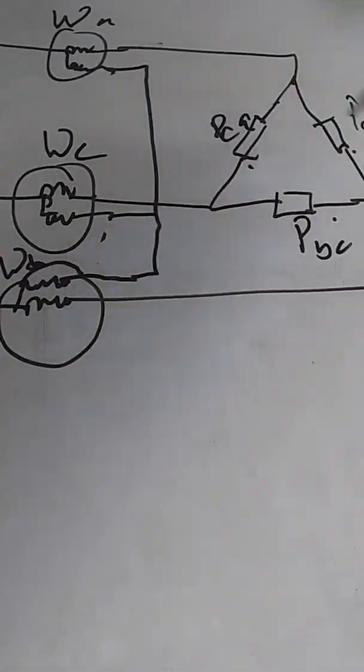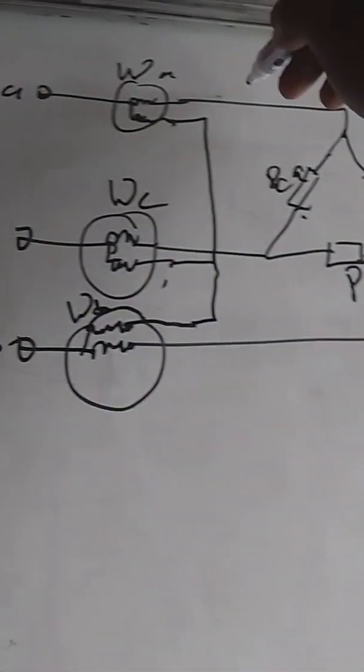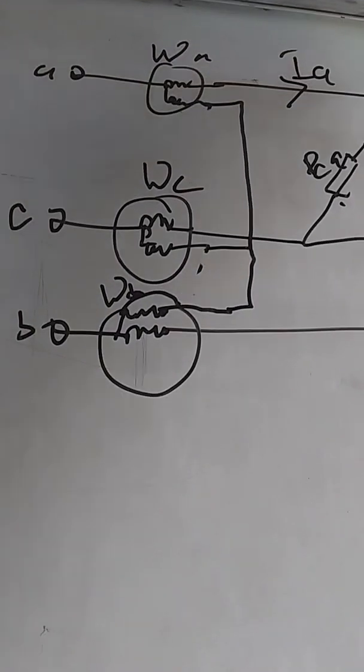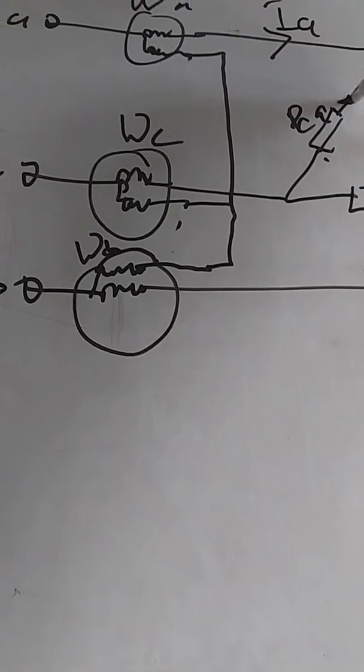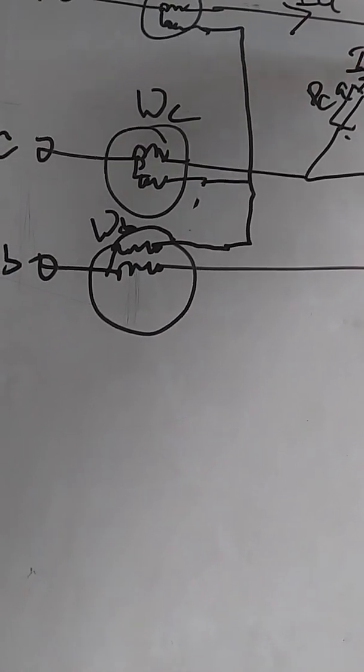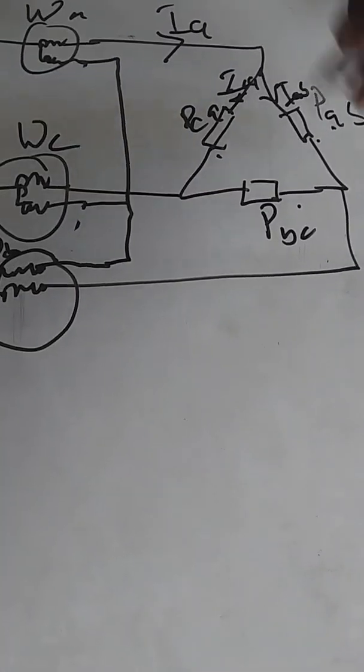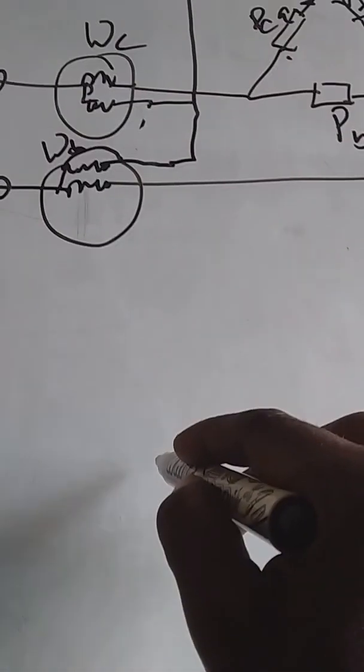I will just give us the basic technicality so that we can go through it. We are to calculate the active power dissipated in each impedance load. Each impedance load, we need to calculate this. And to be able to calculate this, you need to know the current that is going through each phase impedance, then you know the power in each of them. So to be able to determine the power, first let's go and quickly draw the phasor diagram.